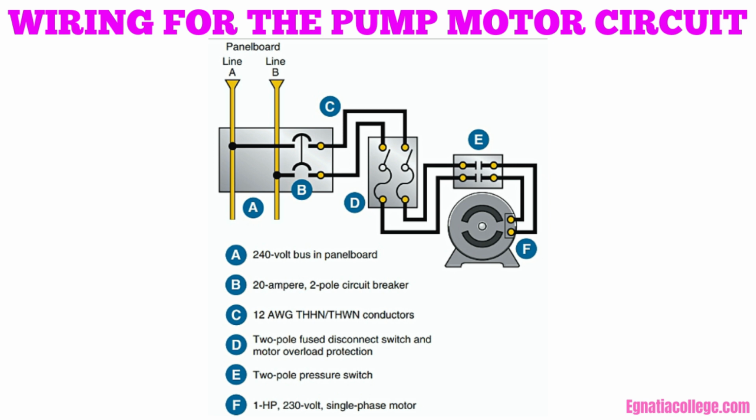to form circuit A5/A7. Dual element, time delay fuses may be installed in the disconnect switch. These fuses will serve the dual function of providing both branch circuit overcurrent protection for the pump motor and backup protection for the thermal overload protecting the motor. These fuses may be rated at not more than 125% of the full load running current of the motor.